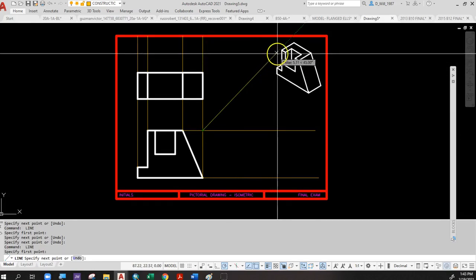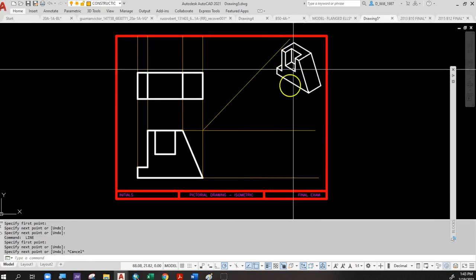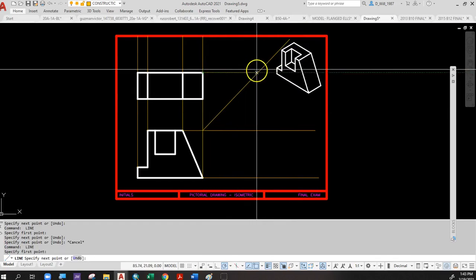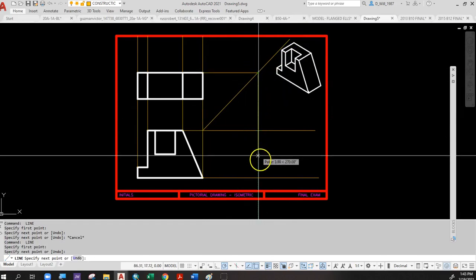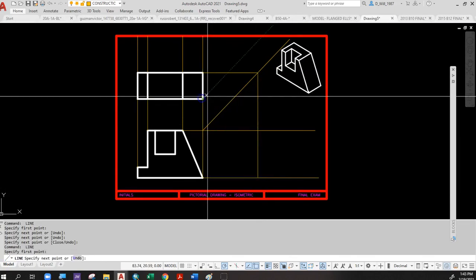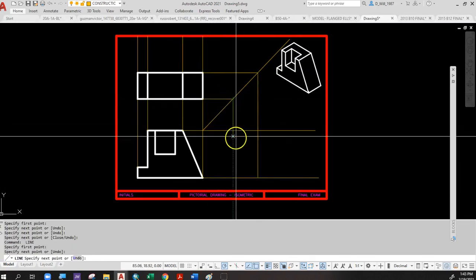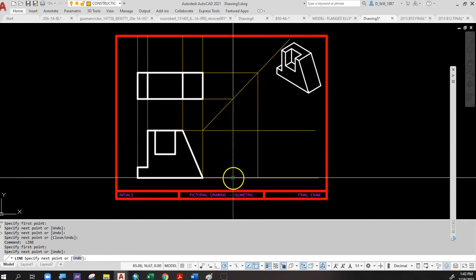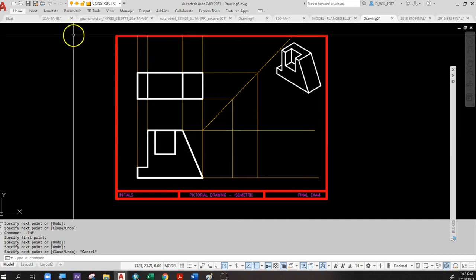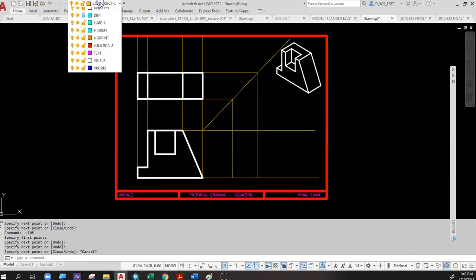And then to get the top view into the side view, or to get the side view into the top view, you might remember this little thing called the miter line. And the miter line lets you take your measurements and locations from the top and telegraph them into the side. So we're taking that dimension for the depth and we're wrapping it around a 90-degree corner. And that gives us the same exact size over here. So you don't have to go in and measure things from scratch.